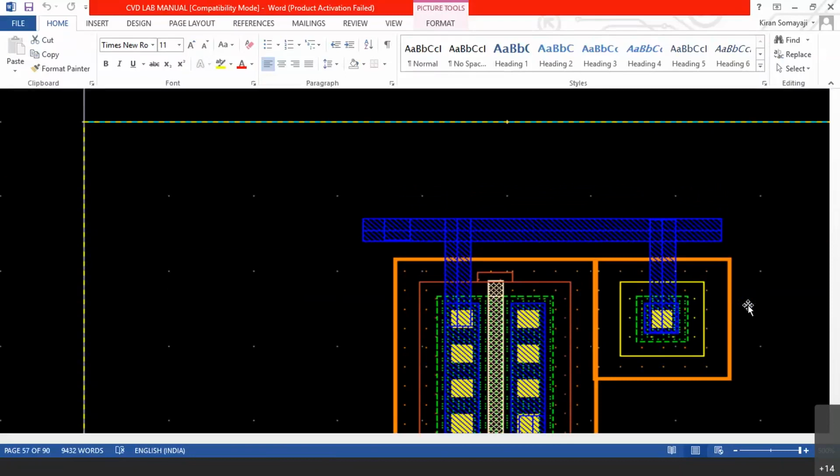We did not produce a PN junction on our own. It was produced because of our processes. So when you look at an N-well process, you will see so many parasitic diodes there. Between a substrate and a well, you have a PN junction because substrate is P-type and well is N-type. You will have a PN junction there. That is a diode. We did not want a diode there, but because of our own process, diode was formed. That diode should never conduct.